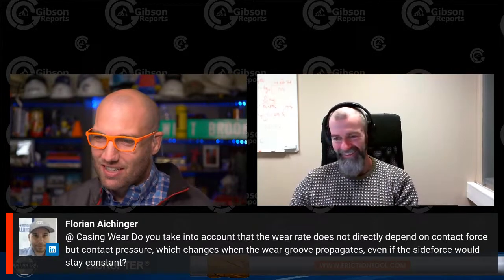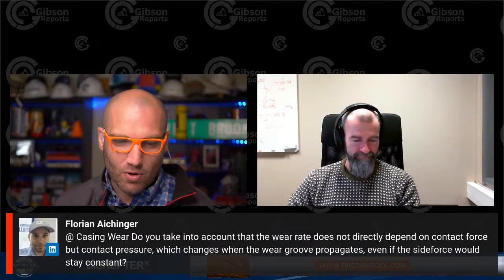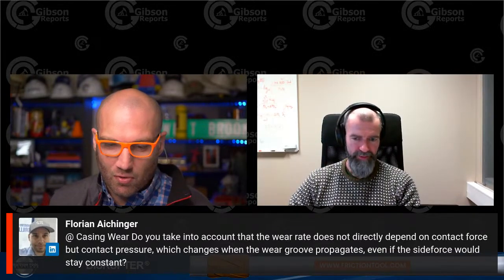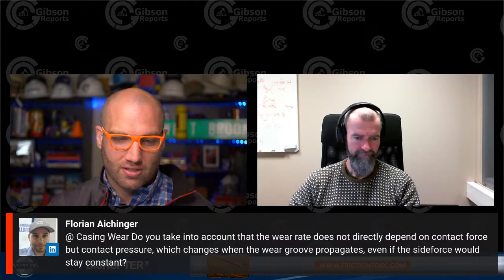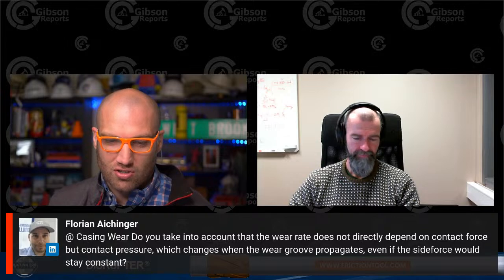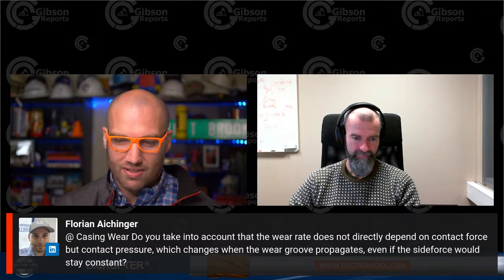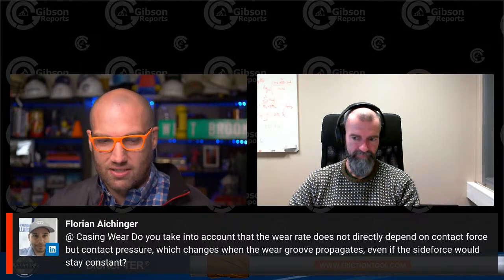I could not have explained that, but yes, thank you for doing so. All right, Flora says, casing wear, do you take into account that the wear rate does not directly depend on contact force, but contact pressure, which changes when the wear groove propagates, even if the side force would stay constant?